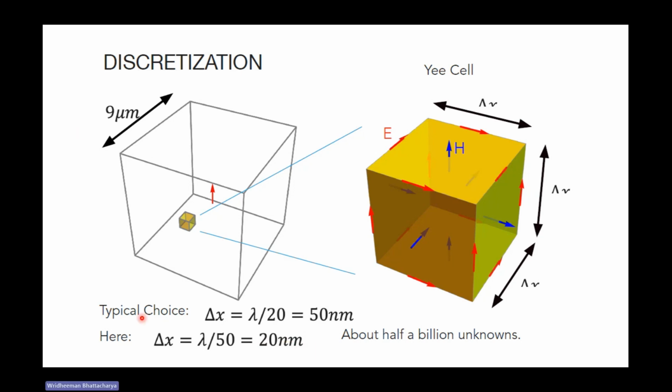So this is the general principle upon which these things work. We just discretize it and see how each space is working, and for this del x, how to calculate the length: it will approximately be the wavelength of the light divided by 20 or 10. Dividing by 50 might be too small in some cases, increasing the time too much.